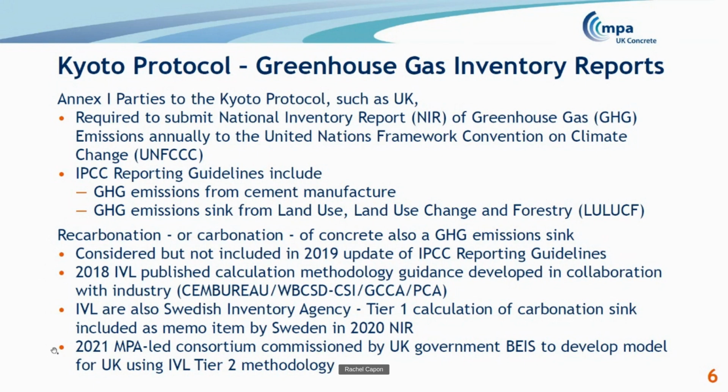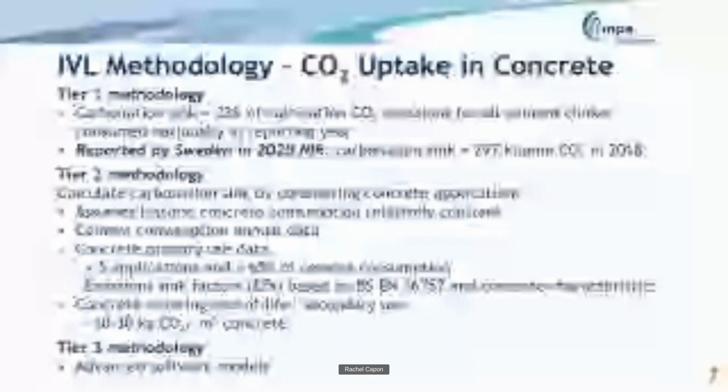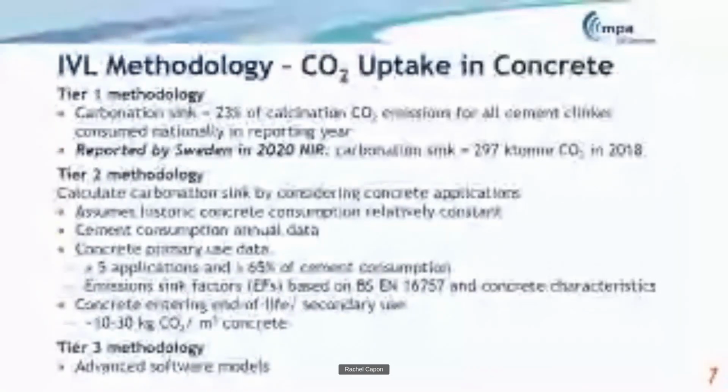Last year, MPA was commissioned by the UK government, by BEIS, the Department for Business, Energy and Industrial Strategy, to develop a model for the UK. BEIS were very keen that we don't just develop a Tier 1 model, but that we develop at least a Tier 2 model. So, in terms of the IVL methodology for calculating the CO2 uptake in concrete, I said it has 3 tiers.